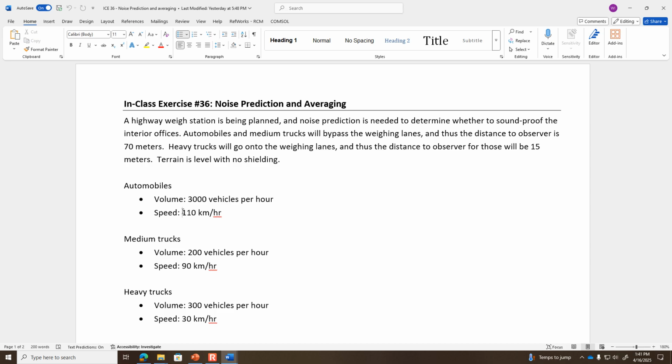So we're going to draw a line from the pivot point through the speed of the automobile, 110, and stop at line A. So just a single line from the pivot point through 110, the lower one for automobiles and trucks, and stop at line A. And you can just, next to that point where the line comes into line A, write A1, very small, not on the intersection point, but just near it.